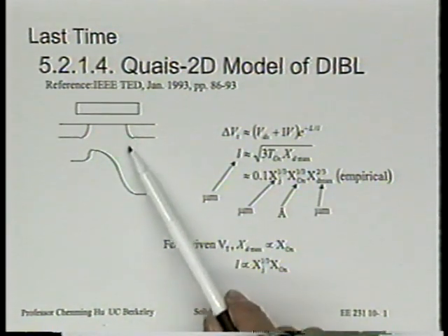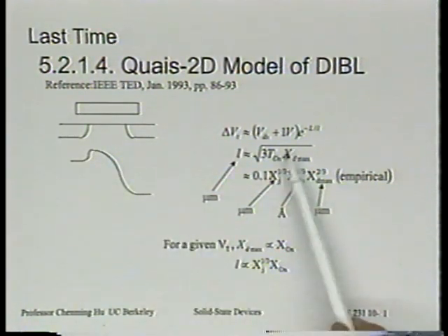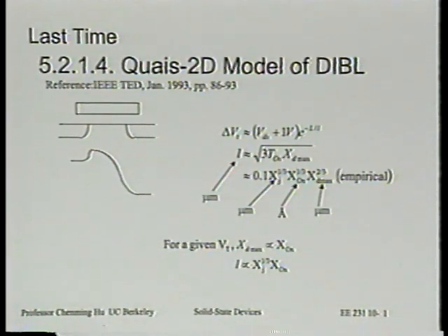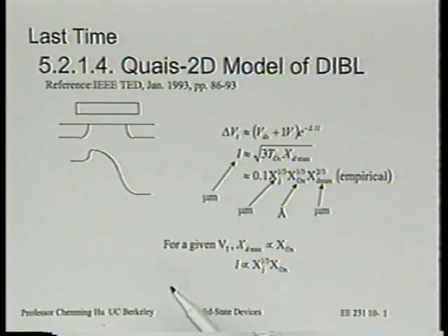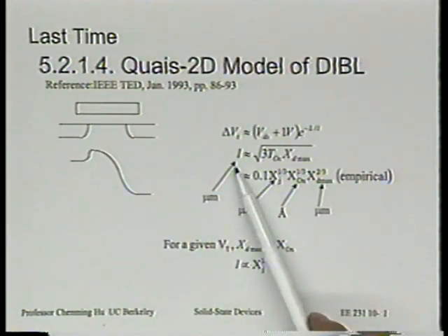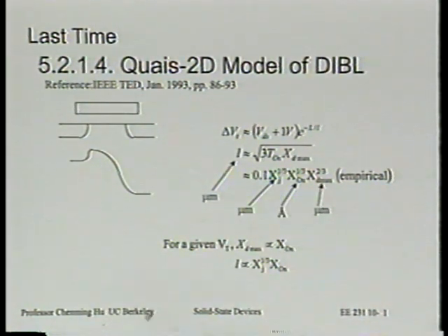If we have large XJ, it will push the bottom boundary away, first of all, right? Well, I would not force this topic too much right now. It's a review, so I would just stop there. So you can think that there's also some impact of XJ, such that in order to suppress the short channel effect, we want thin oxide, we want small XD max, we also want small XJ. That's what we want. All right?